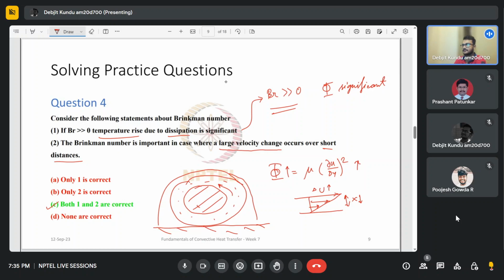So in this case, there is a very high U over here. So industrial shafts and let's say shafts in engines, both in automobiles as well as for Air Force applications. In all cases, aerospace applications, the shaft velocity is actually quite high. So this U would be quite high, and the bearing itself would be at rest. So there will be this huge change in velocity within a very narrow gap.